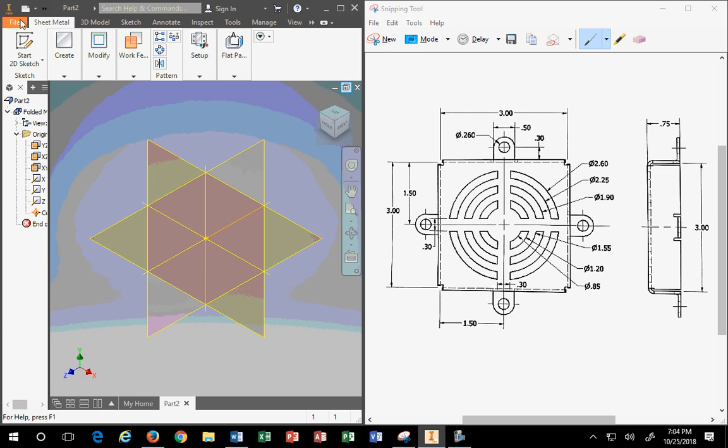And then we look at this body, and we see it's got notched corners. It's got bends in it. Doesn't tell us what radius the bends are, though. Do you notice that? Is the material thickness provided? Let me look at the master drawing on this.